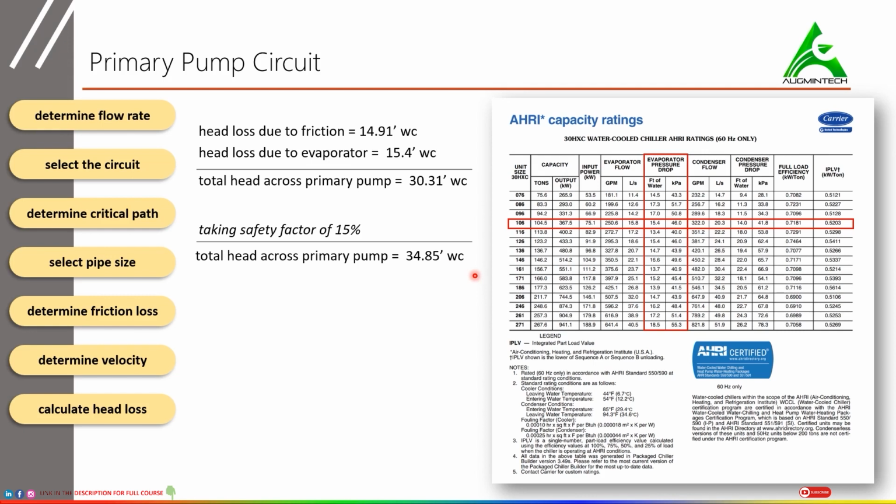All right, great. Now let's move forward and see what we have to calculate next. This is a really important value in the entire calculation that we have done. This is the total head loss due to the pipe, its accessories, and the evaporator coil. So the pump has to overcome this much of friction losses. It is only then possible to circulate water in the primary circuit. So we have followed all these steps. Let's see what is the next step.